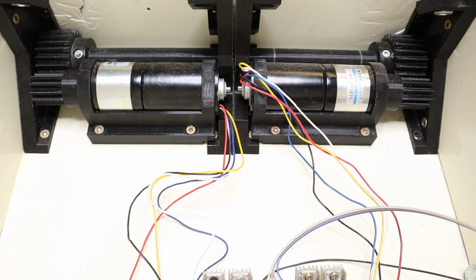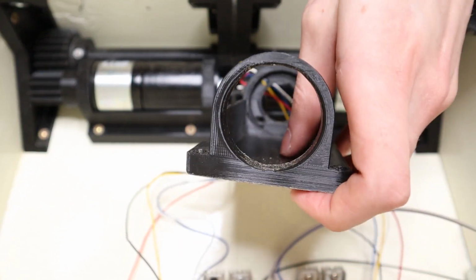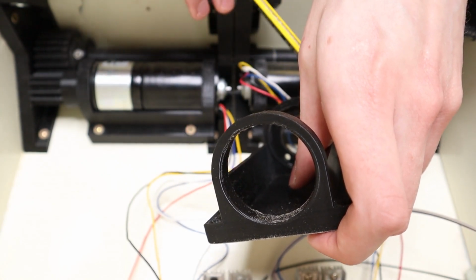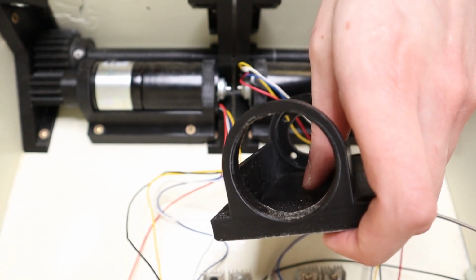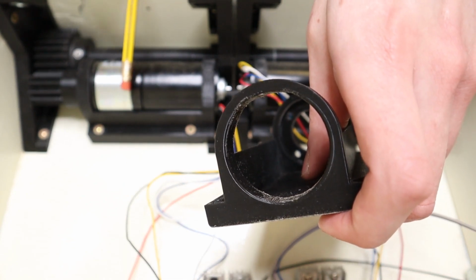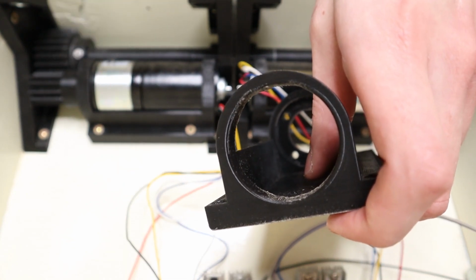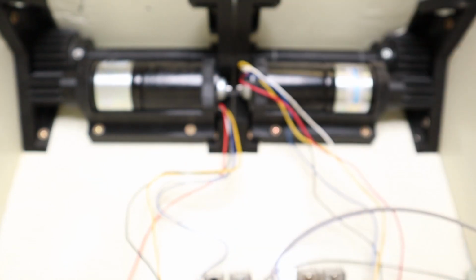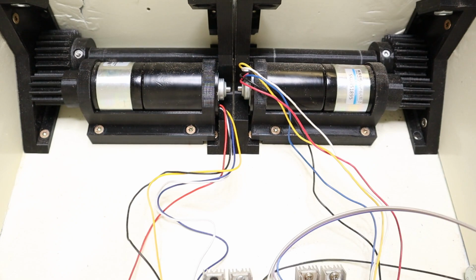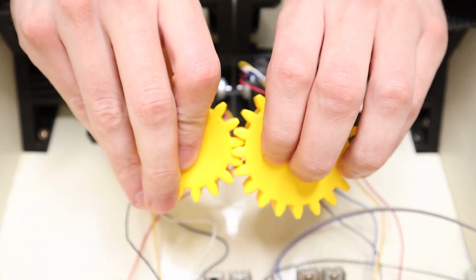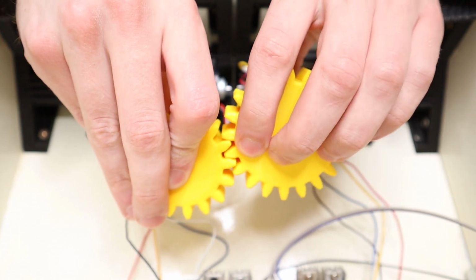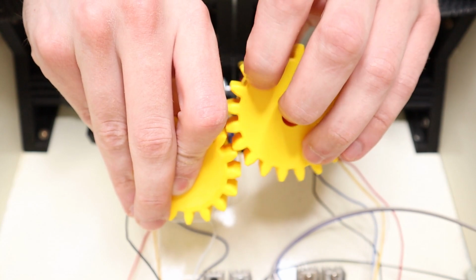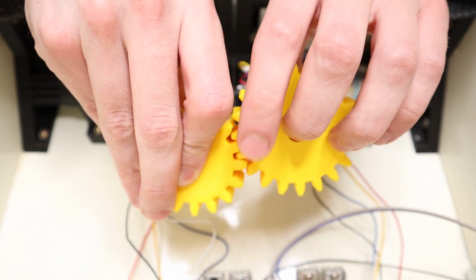And the problem you run into then, when you look at an old version of the motor housing, is that there's just not enough material here to keep the motors in place. And so the motor will actually move away from the other gear slightly, away from the other shaft, and that causes the gears to come apart from each other. And when you look at that, what essentially happens is that the gear teeth will skip like this. And that creates an enormous amount of noise, an enormous amount of wear, and the tank actually doesn't move either.